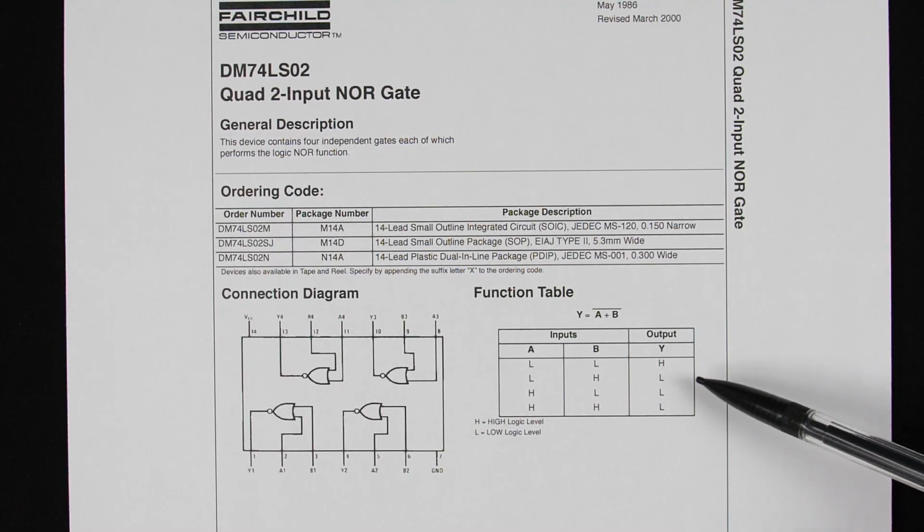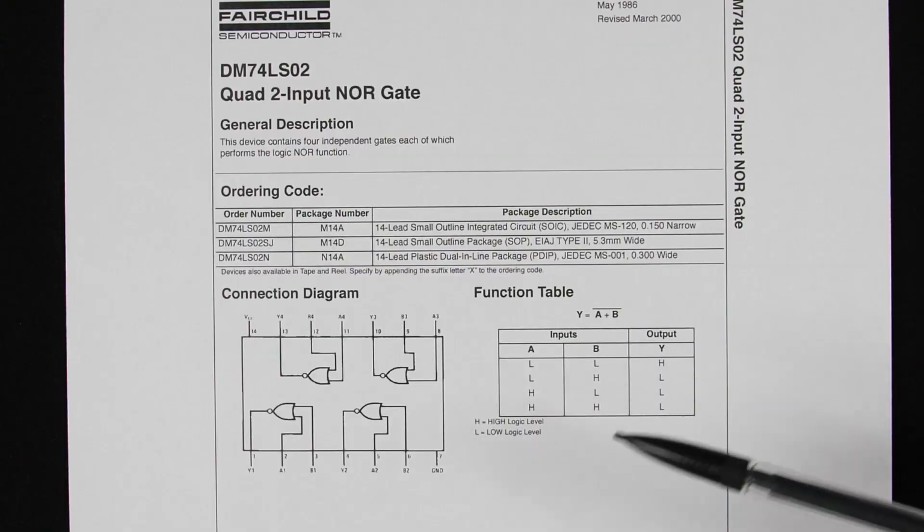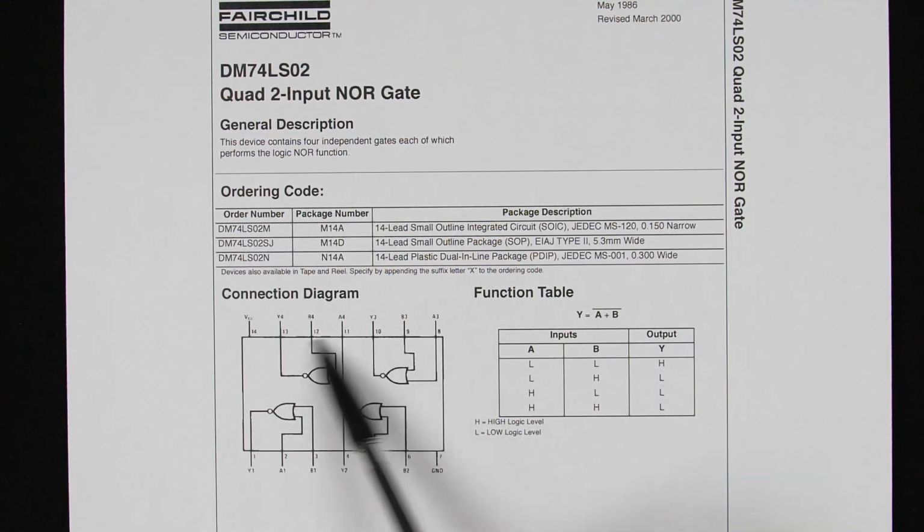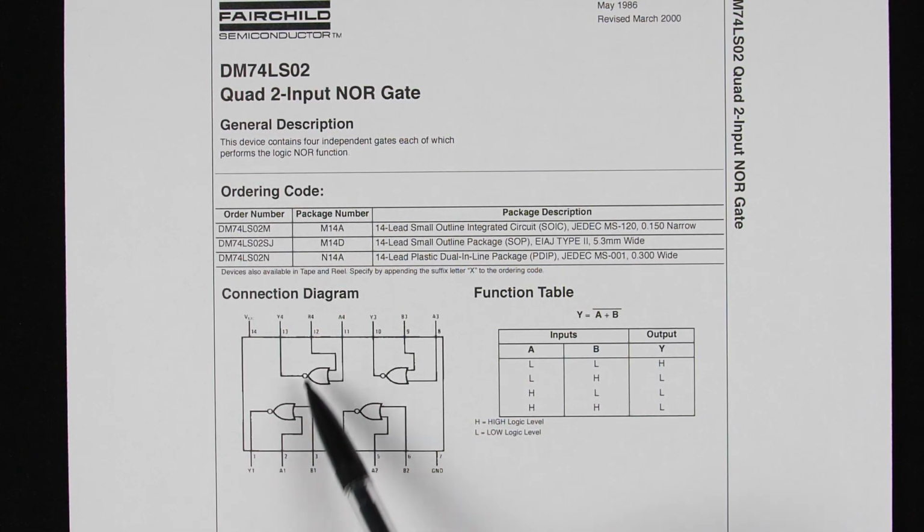Now you can get 8-input NOR gates, and if you've got one, you can definitely use it, but I don't happen to have any, but that's okay. We can actually build it with this one. And this gives us 4 NOR gates, and so what we could do is hook 2 bits up to each, and then that will tell us if each pair of bits is 0, and then as long as all of the pairs of bits are 0, then we'll know that the whole number is 0. So we need to take the outputs of these 4 NOR gates and AND them together.